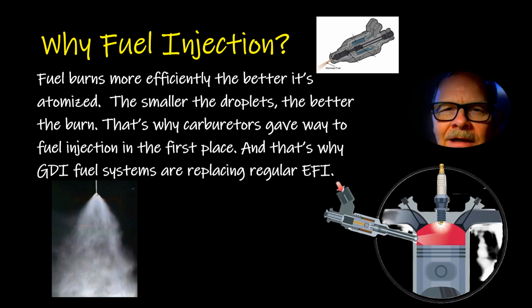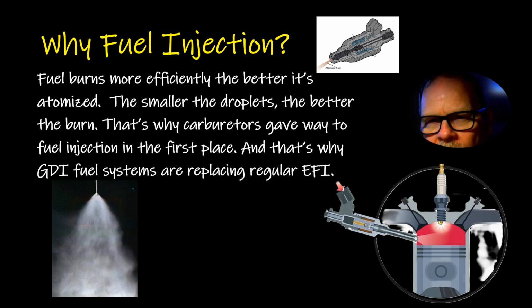On the gasoline direct injection systems, the engine controller can decide when to squirt that fuel in there, no matter where the valves are, how much to put in there, and how to squirt it in there. They can have a stratified or a homogeneous charge, or a mix of either of those two. It's a good, efficient system. Now, there are problems with it.